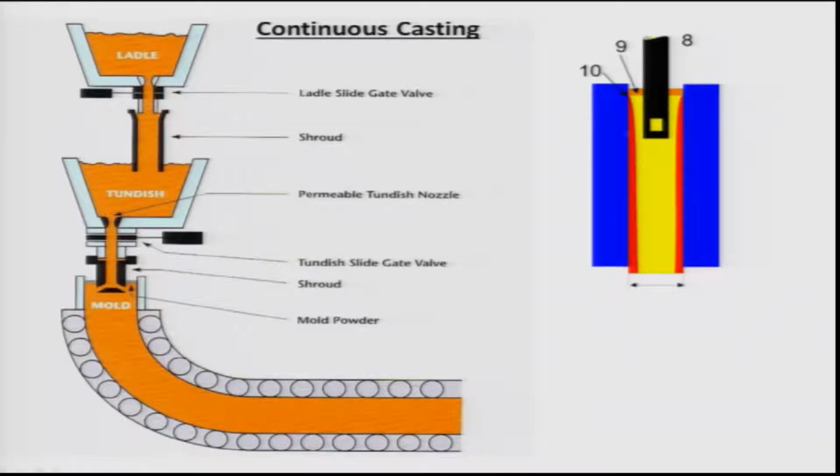So the number of sites on which nucleation can happen is also very large. Not only that, because it's a rapid cooling process, the sizes of the grains which may form along this interface are very small. Subsequently, as the liquid metal flows by on the conveyor belt, water is sprayed onto the surface so that heat can be extracted and everything is solidified at the end.